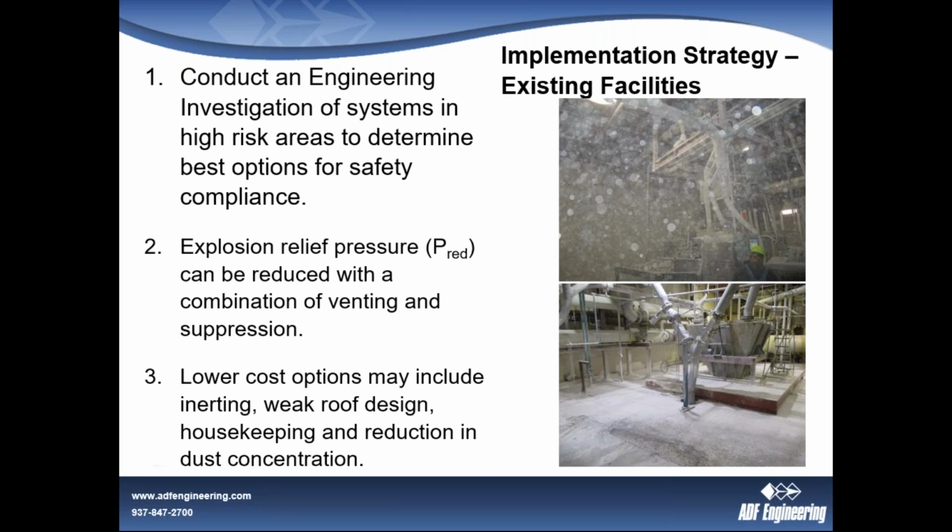So by going to a neutral third party, such as a qualified engineering firm, you'll get some other ideas that may not involve some of this expensive equipment, such as the ability to operate below explosible concentration, the ability to operate above the PMAX, or to design your equipment above the PMAX.